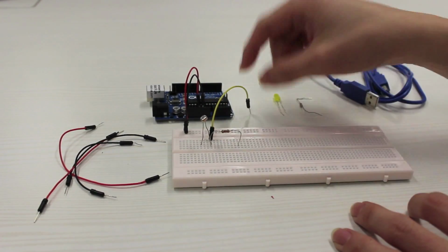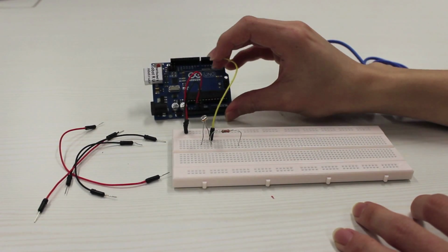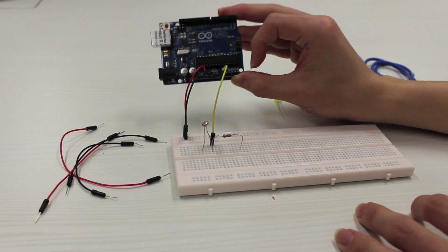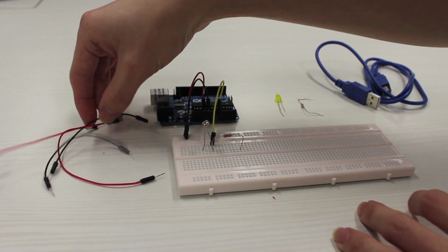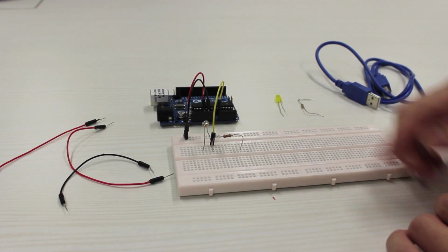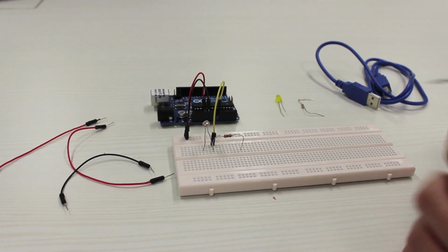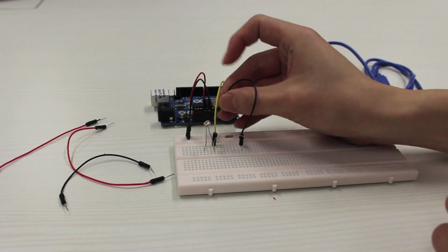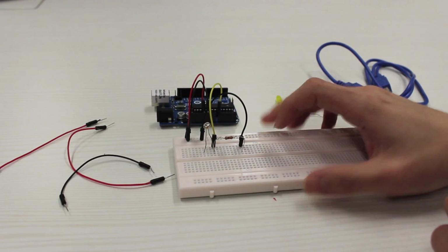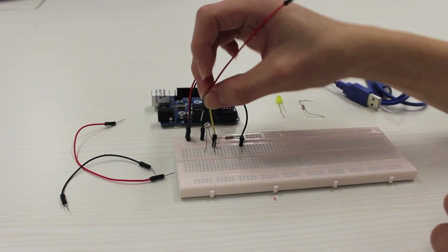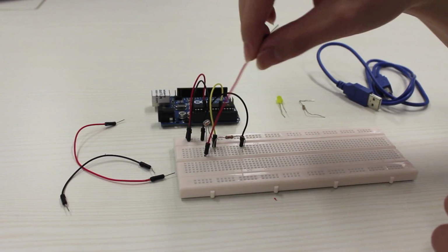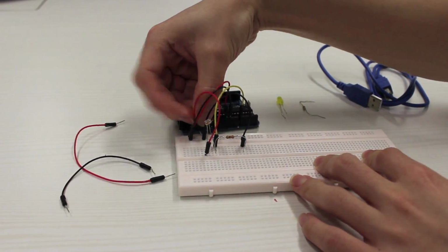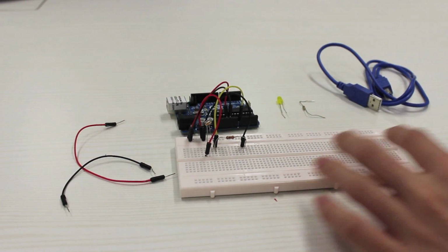The Arduino measures the voltage at this point by using the analog pin, and in this case, the A0 analog pin. Next, we need to power the voltage divider component of this circuit, and to do that, we connect the resistor end to the ground of the breadboard. Next, we connect the LDR end of the potential divider to the 5 volts on the breadboard. We are now done with the input section, which is the LDR.